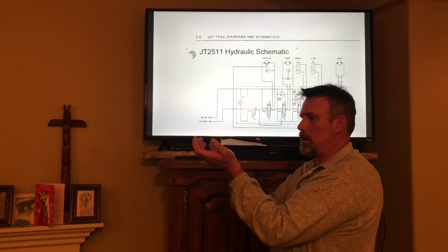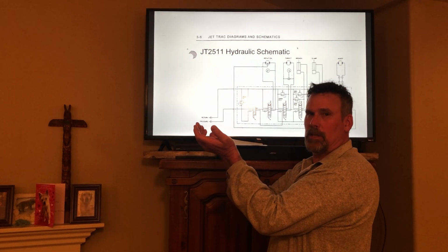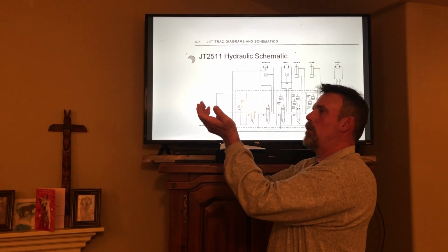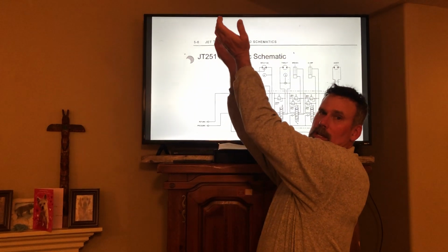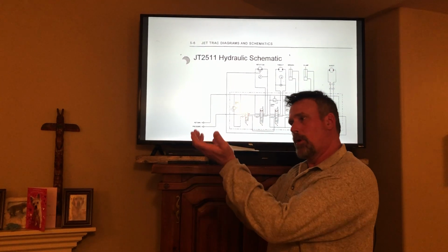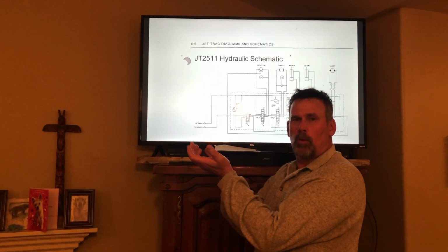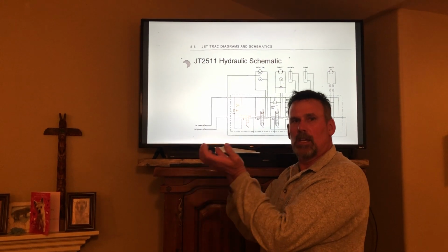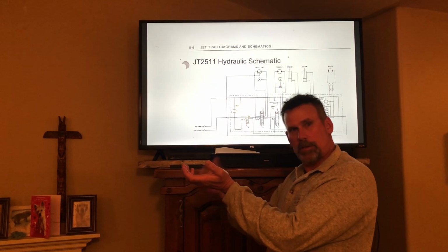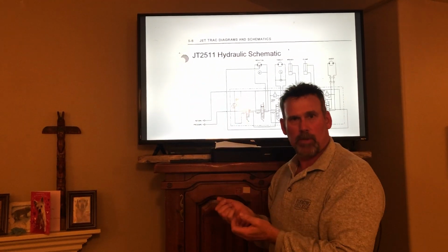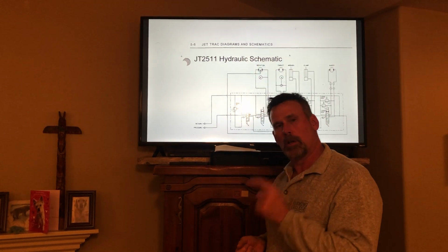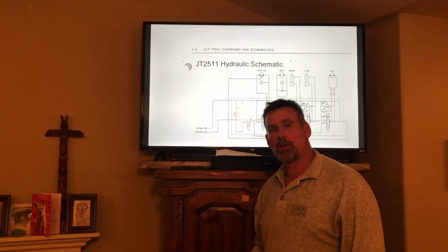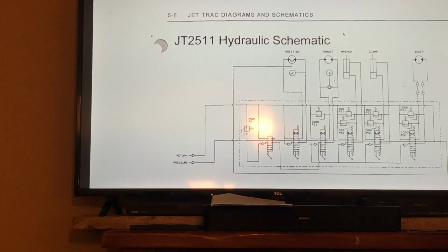And then the pump will start to catch up and it will go 1200, 1500. And when it gets to 2000 PSI and above, now it can start to raise that. And it can raise it and lift, and I can dump it in the truck. But we don't want that drop when we first pull the lever, okay? We want our load to stay in the same place until the pump pressure builds and can raise it further, okay? We don't want that drop. So that's why we put a load check valve in the system to hold that, okay? So let's go to the schematic and we'll explain that further.